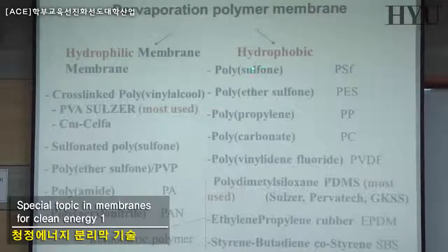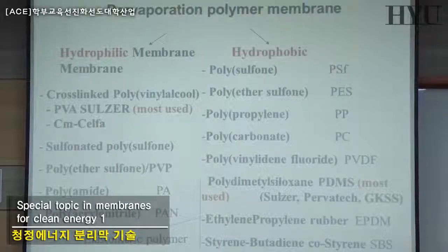You can make the polysulfone as a hollow fiber, but it's very difficult to make hollow fiber out of the sulfonated polysulfone because it's water soluble. Okay, it's not water soluble, but it's organic soluble. So the process might be a little different. Polyamides are hydrophilic. If you put polyvinyl pyrrolidone in polysulfone, yes, you can make it hydrophilic.